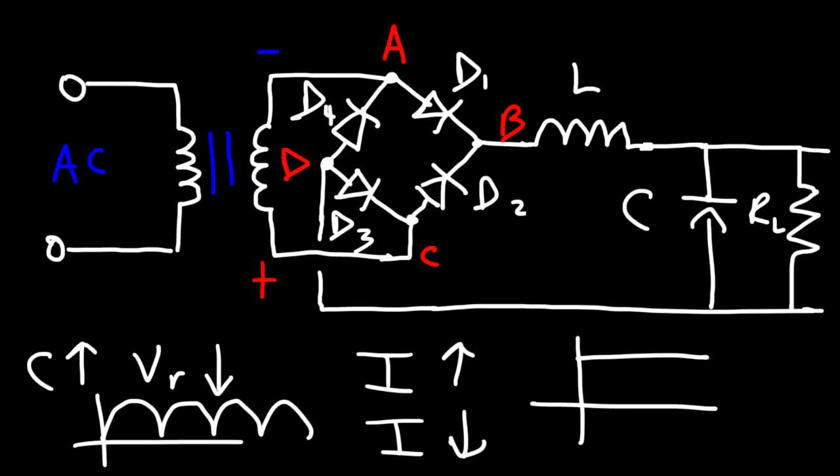So therefore, the inductor, when placed in series with a circuit, will allow a steady DC current to pass with no impedance. However, it will oppose a pulsating DC signal. So thus, the inductor will help us to create a more stable DC output, which is what we want.